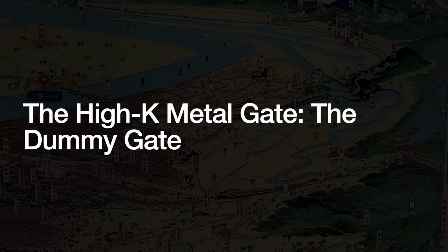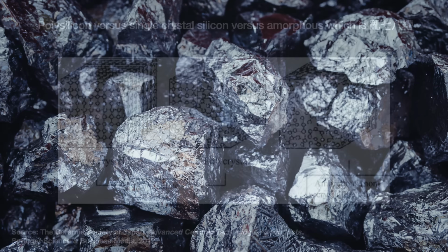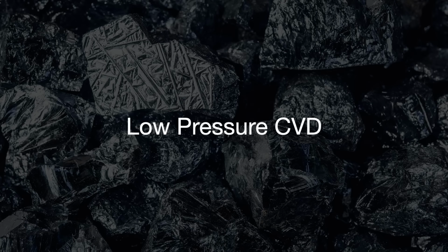Unlike the silicon substrate below it, which is made of single crystal silicon, the dummy gate is made from polysilicon, called as such because it is essentially many small silicon crystals separated by grain boundaries, so still more organized than amorphous silicon, which is just a jumble, but with less strict crystal demands, so we do not have to use Czochralski to make it. This polysilicon is deposited using CVD again, of course.